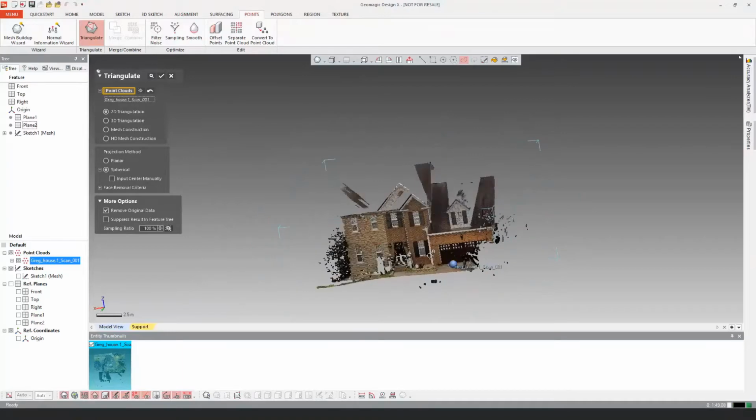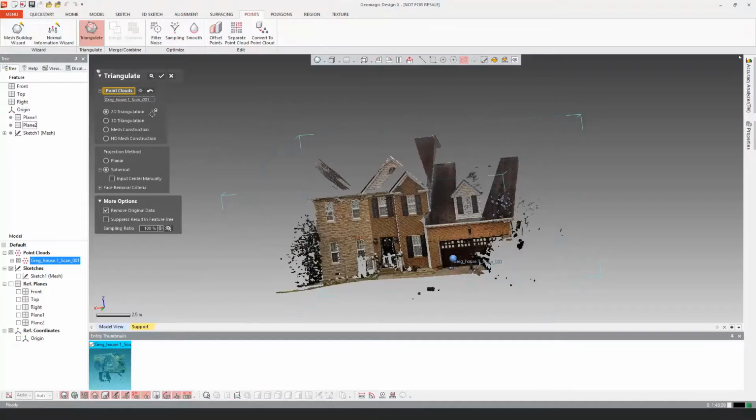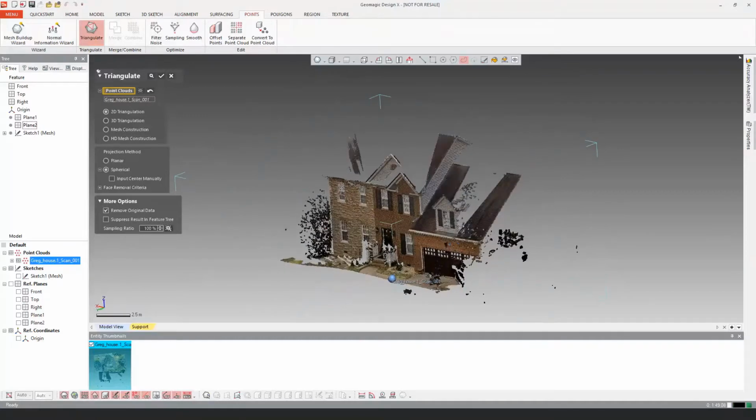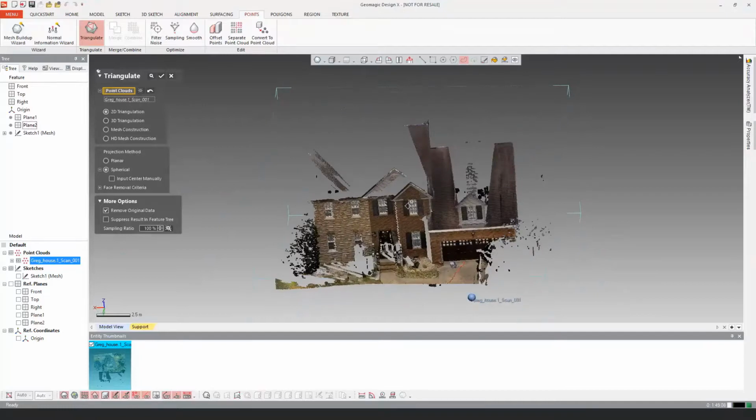So you can actually really end up with some nice surface data, and you will notice when you run stuff like this 2D triangulation and this method, some things of high incidence angle, like leaves on this tree where the scanner was hitting them pretty flat, they will get edited out of the scan data essentially, because it'll say the accurate positioning of something like that with such a high degree of incidence to an almost planar tree leaf that's in the wrong direction, or the top of a banister or something like that, isn't necessarily going to be an accurate measurement. So it could pull some stuff out like that for you, and it's very handy if you have a lot of scans and some very complex geometry.